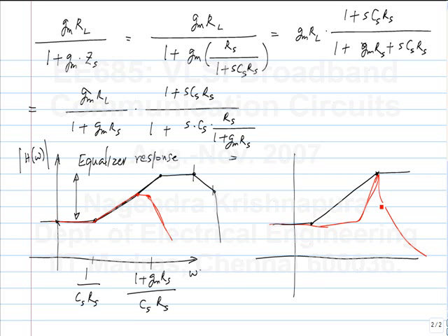So if you use a very high order system, you can get very large boost, but that will be a sharp peak, whereas you want boosting over a wider range of frequencies. So this is for the first order system, it goes up at 20 dB per decade. But if you look at the attenuation of a transmission line, that's about 10 dB per decade. There are various causes for attenuation of a transmission line. There is series loss and shunt loss and so on. But because of series loss, the attenuation will be about 10 dB per decade. So you want a gentle boost, but over a wide frequency range. You don't want a very sharp boost.